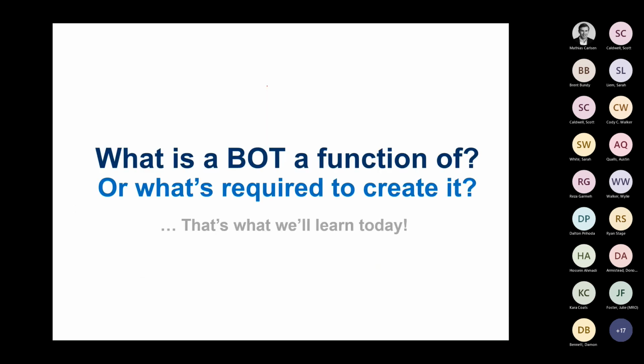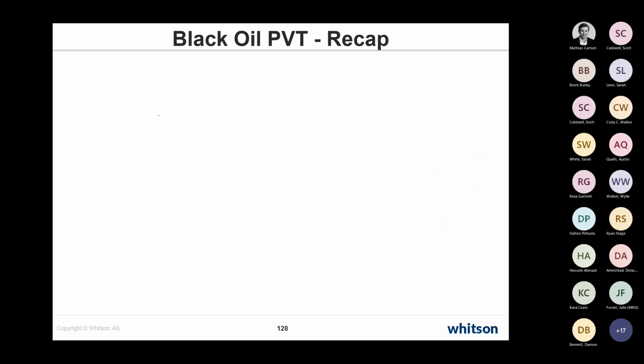What's required to create a black oil table is what we're going to talk about in this session. You need an equation of state, you need a temperature, you need a composition, and you need a surface process. Those are the 4 things really required to create a table. In the software, you have the equation of state, you input a temperature, you're using, for instance, GOR to predict composition. And then we looked at that just before this bomb thing happened with the surface process, right? We changed the surface process, and that's also an input to creating the tables. That will change your PVT properties.